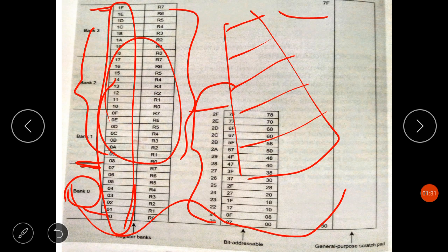So what will happen if in a program more than 24 bytes of stack memory is needed? As you can see, 08 to 1F makes up only 24 bytes. Each address is a 1 byte memory location, so from address 08H up to address 1F there are 24 bytes of memory location.